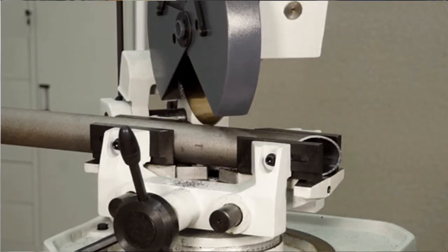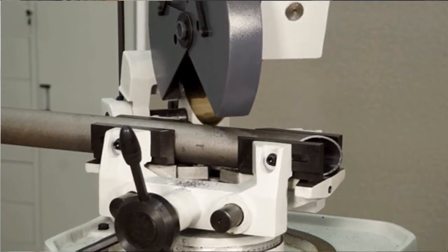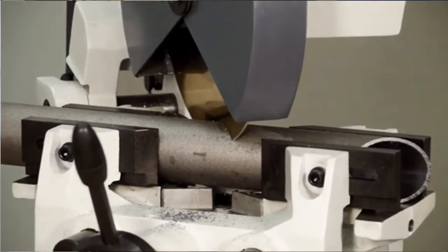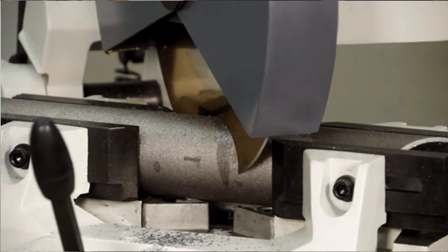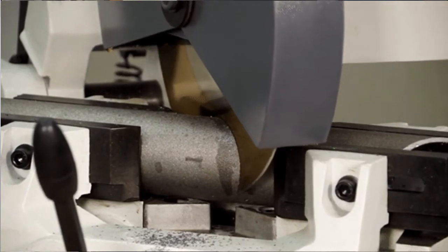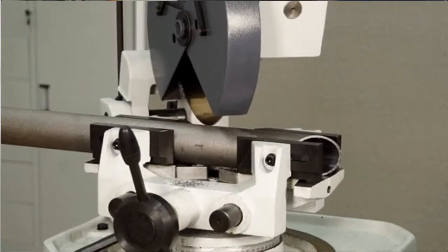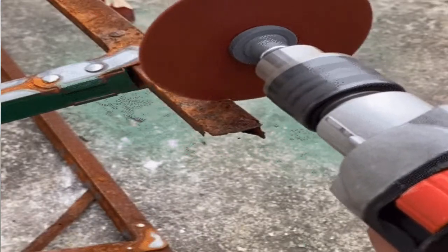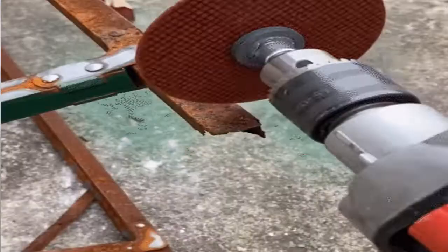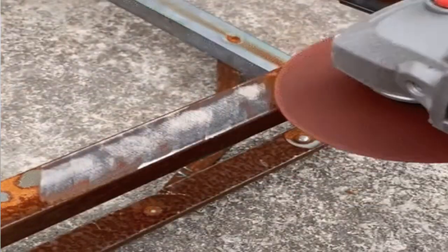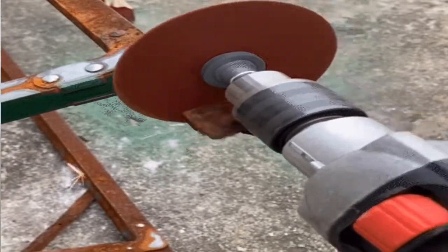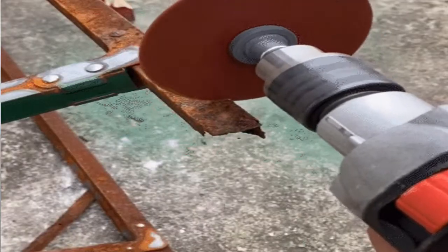Circular sawing uses a rotating saw blade to provide the continuous motion of the tool past the work. Circular sawing is often used to cut long bars, tubes, and similar shapes to a specified length. In abrasive cutoff, an abrasive disc is used to perform cut-off operations on hard materials that would be difficult to saw with conventional saw blades.